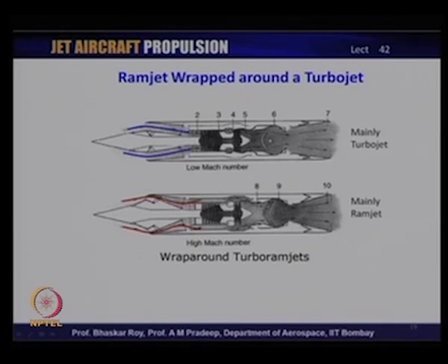Then it goes through the jet pipe and the nozzle of the turbojet engine, which is placed pretty close to the nozzle of the ramjet engine, and operates in a manner that is convenient to the turbojet engine operation, which means the flow could be going straight out without going through a convergent divergent nozzle. So, this nozzle could be a straight out nozzle, or a divergent nozzle coming through the convergent nozzle, and then from here onwards it is a divergent nozzle, which allows the aircraft to fly straight through from subsonic to supersonic flight operation. So, you could have an effective convergent divergent nozzle. That means the nozzle of the turbojet engine is essentially convergent, and then through the nozzle of the ramjet it could become divergent, producing thrust for the entire aircraft.